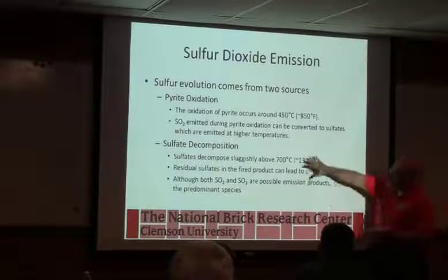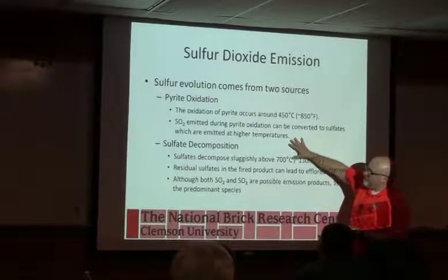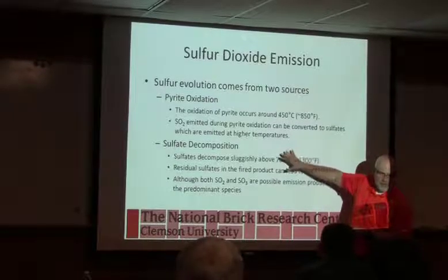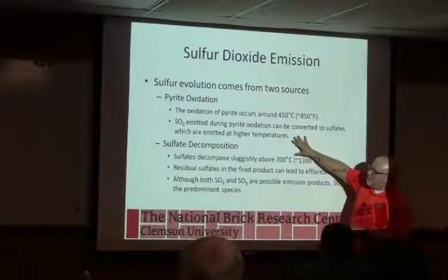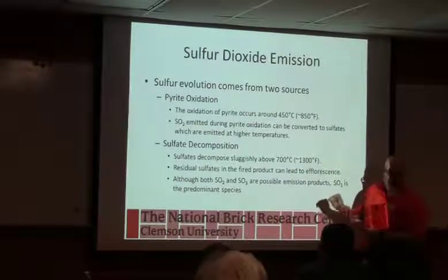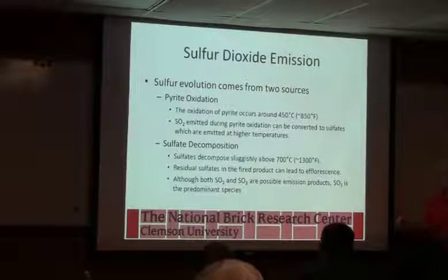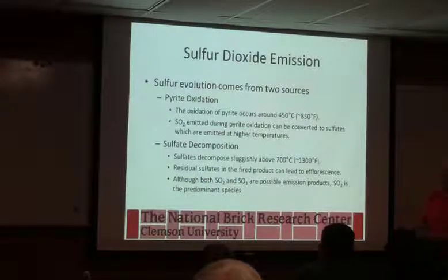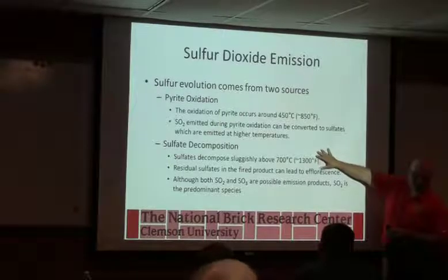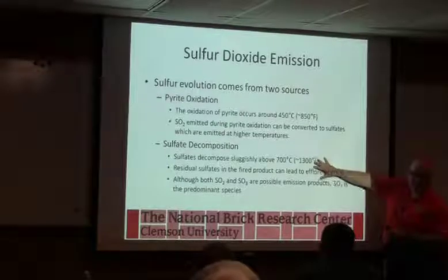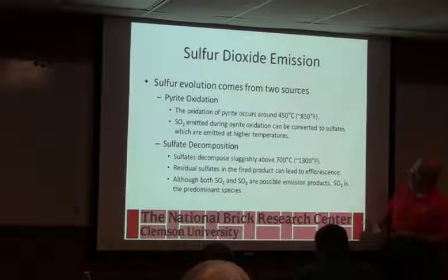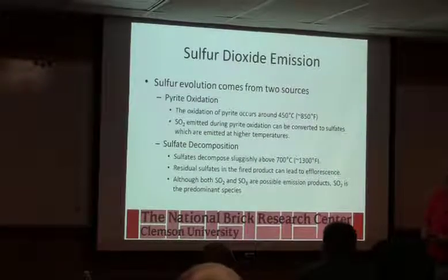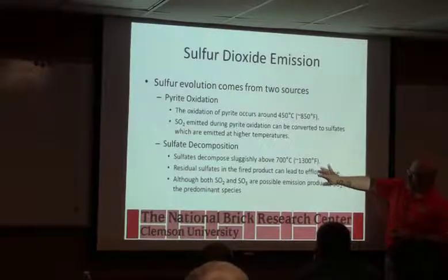So we're happy for fluorine and chlorine when we get retention because it doesn't hurt us. It just cuts down on emissions. Sulfur, you're always better off getting it out of the body and dealing with it in a pollution control device or something, because any sulfur you leave behind in the body tends to be an efflorescence risk. So if you don't want to see efflorescence, it's best if you can get it out if possible, although this is not easy to remove.